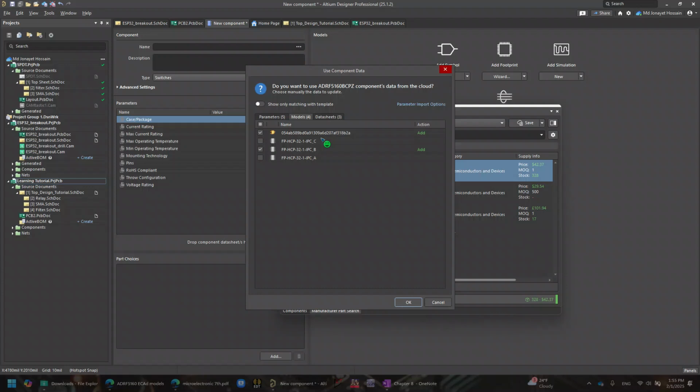Sometimes you have a very tight component and tight board, and you want your components to be very tight, so you don't want a lot of space around one particular component. So in a very tight situation, you want to follow the exact recommendation from your vendor, right? And that time is good. It kind of depends on your soldering capabilities, right? So I'm just going to go with B because I feel like mine is maybe nominal. I don't want to have so much space, and I don't want too little space. Yeah, I'm okay with both.